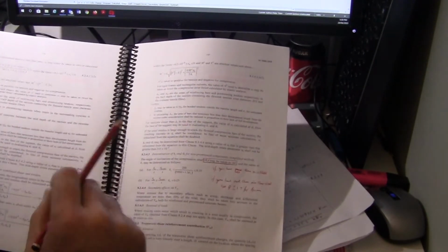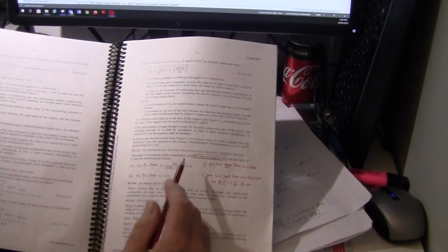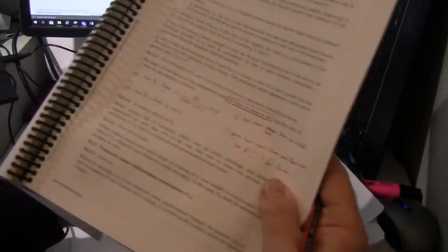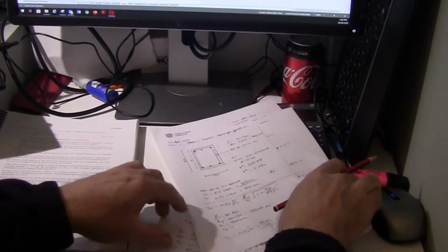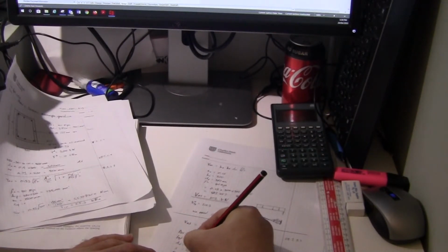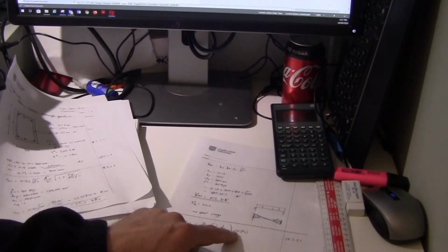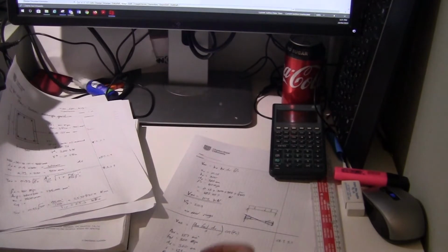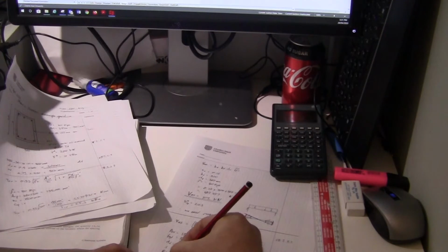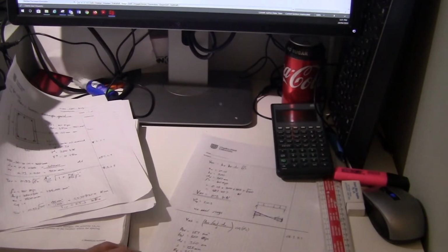But in the simplified method, as long as we comply with all those conditions that we read out earlier, we can use a theta V of 36 degrees. That is the simplified and slightly conservative method. Now you notice we take the cotangent. The cot of an angle is 1 over the tan of that angle. Cot theta equals 1 over tan theta.